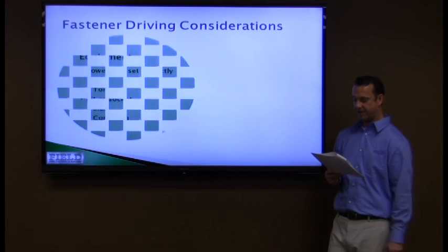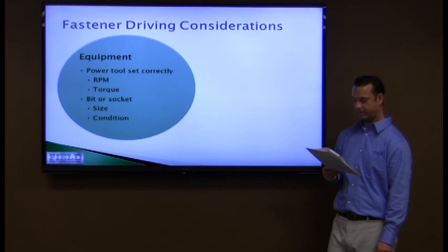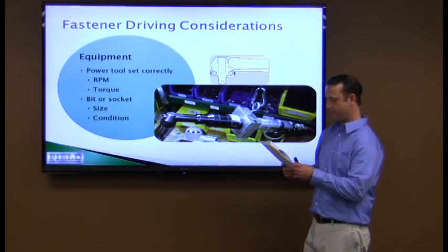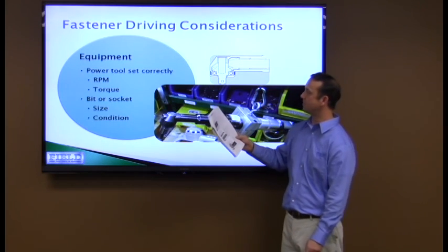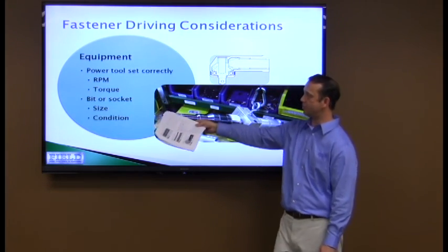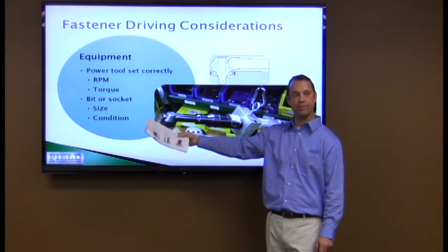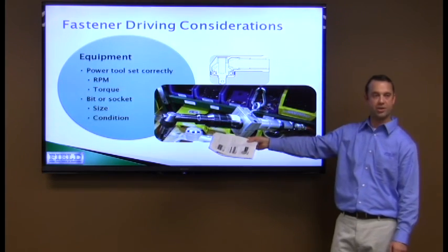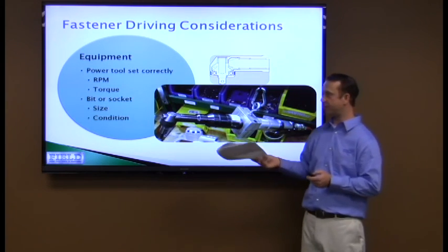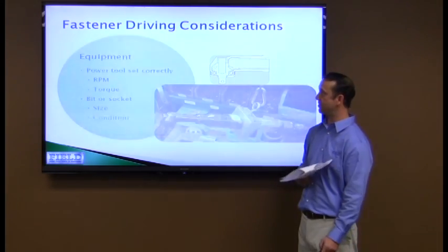Talking a little bit about fastener driving. If you're having failures in the line, look at your assembly tools. Look at the torque, look at the RPM, look at your bit right there, look at the condition of it. Just adds to variations in your fastener process.